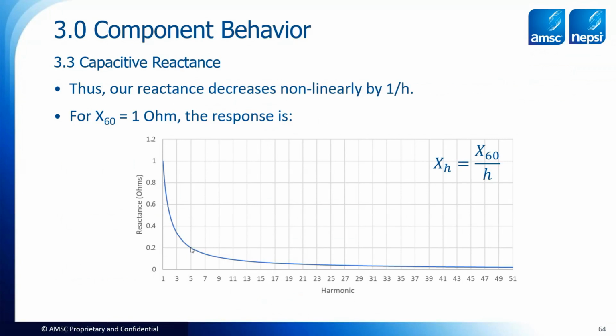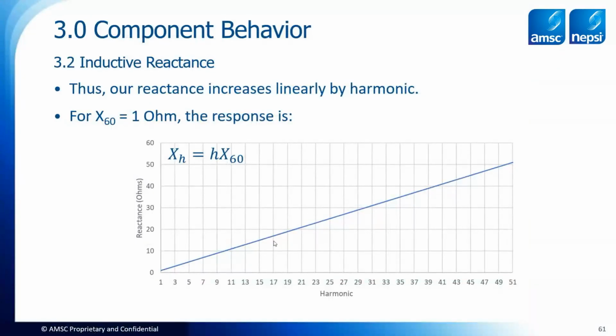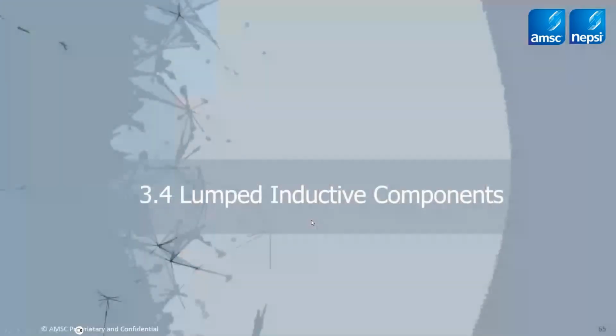So these are basically 2 of the fundamental relationships in all harmonic simulations. There just happens to be a lot of them. So if you build your network and you have a lot of these impedances in there, you'll find that they begin to interact with each other in interesting ways. But at the ground floor, if you do a harmonic simulation into a capacitor, you had better get this answer. And if you do a harmonic simulation into a transformer that has reactance, you'd better get this answer, okay?